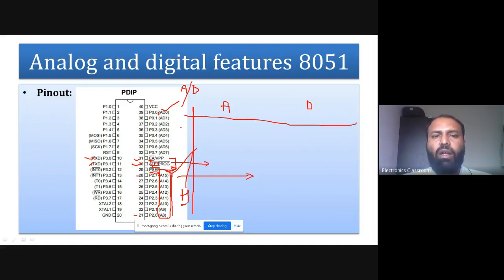So how will the microcontroller or any other device understand at which time instance there will be an address and there will be data? The address latch enable pin will play a crucial role in differentiating address or data. Typically, whenever those pins are carrying address, the address latch enable pin status will be high.